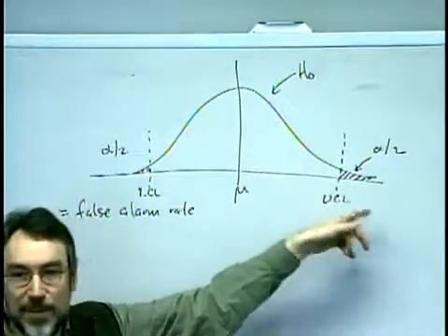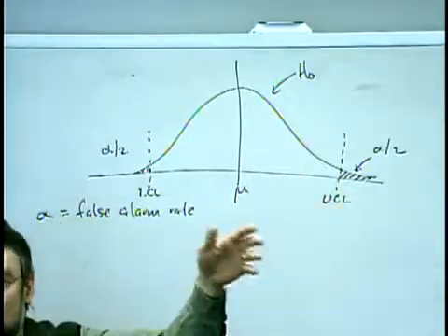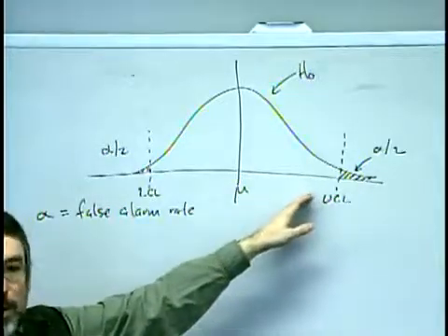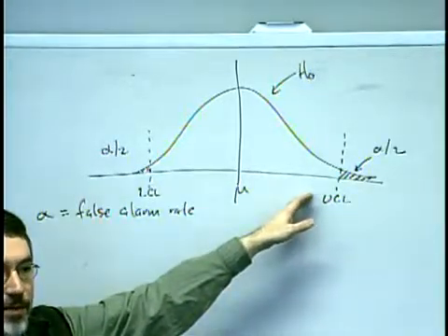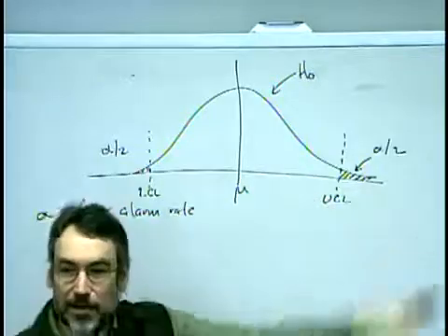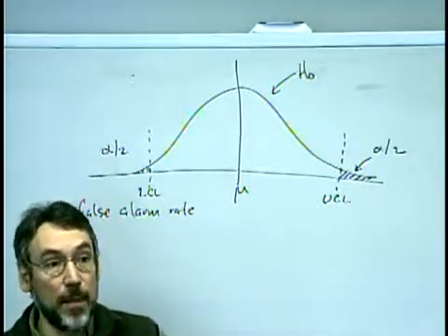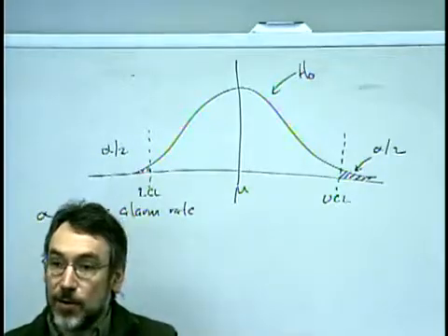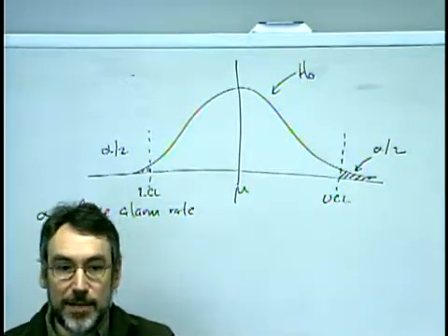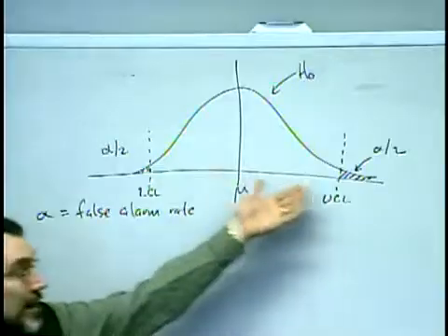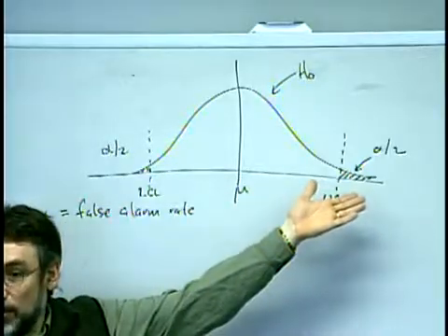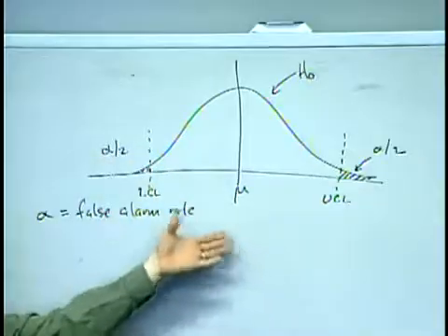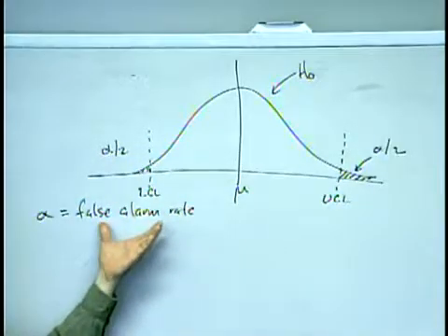And if we do 3 sigma, we saw that about 3 in 1,000 points will fall way outside in the tails. So when we get a point out in the tail, we say, something might be unusual going on. Either something has changed in the process, or I got unlucky and I just pulled a sample from the tails. So in fact, in a process that's always in control, there is this false alarm rate.